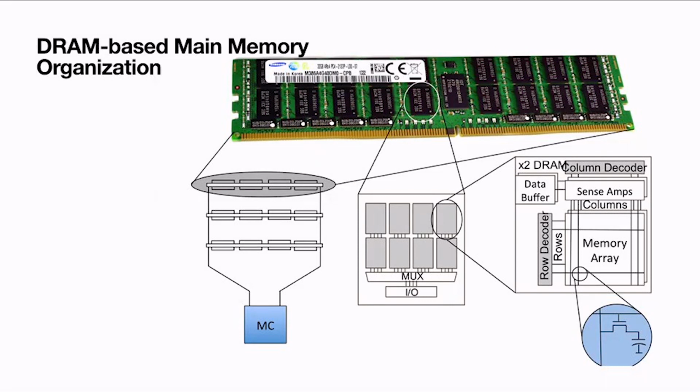Unless you store the actual value back into the capacitor, next time if you want to come back to this DRAM cell, it is not going to give anything. Because you already read the entire charge in the capacitor, now you have to restore the charge back. How do I restore? Once I send the data to the sense amplifier, the sense amplifier says this is logic 0 or logic 1, and then I again write the appropriate charge into the capacitor. That is the restore operation.